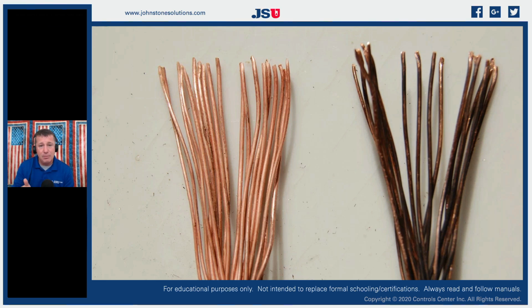It didn't affect it much because the oxidation created a nice thin layer of protection over the copper, and it didn't interfere with the way the current was flowing through that. But if we reuse that exact same wire that has oxidation and corrosion on it, and we turn that into a communication wire instead of a current wire, now all of a sudden we have some problems with that patina